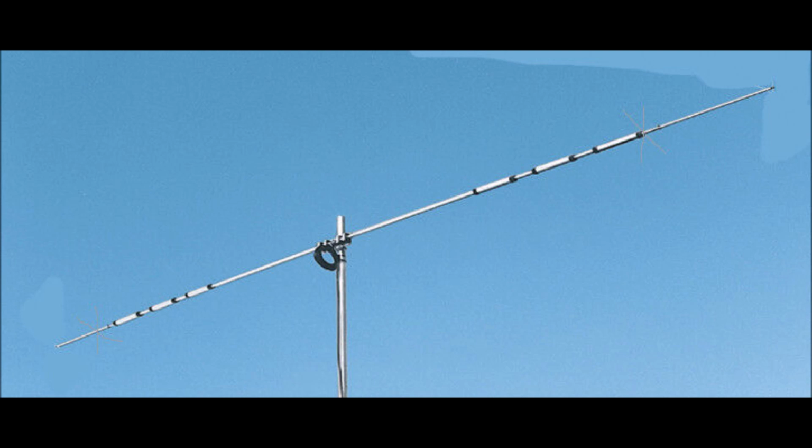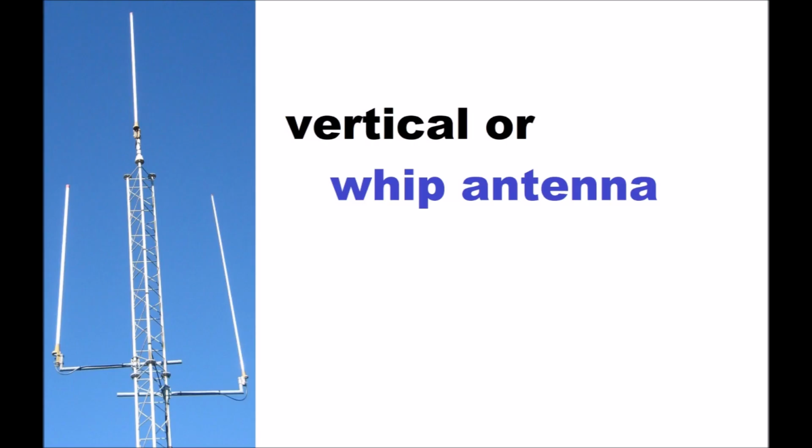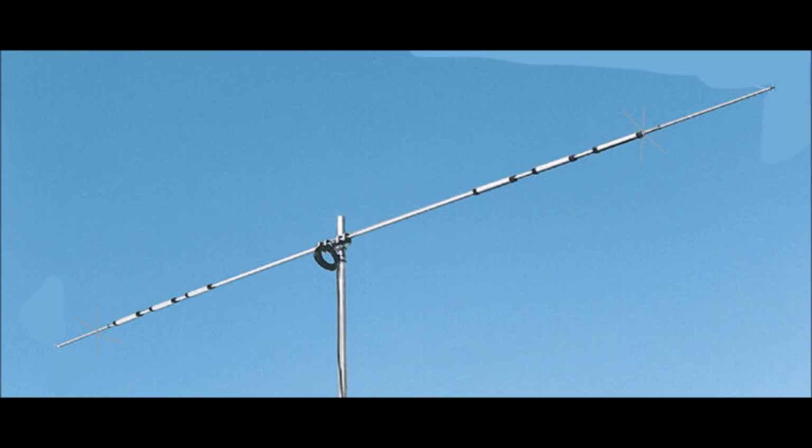The dipole antenna, which is the basis for most antenna designs, is a balanced component with equal but opposite voltages and currents applied at its two terminals. The vertical antenna is a monopole antenna, not balanced with respect to ground. The ground, or any large conductive surface, plays the role of the second conductor of a dipole.